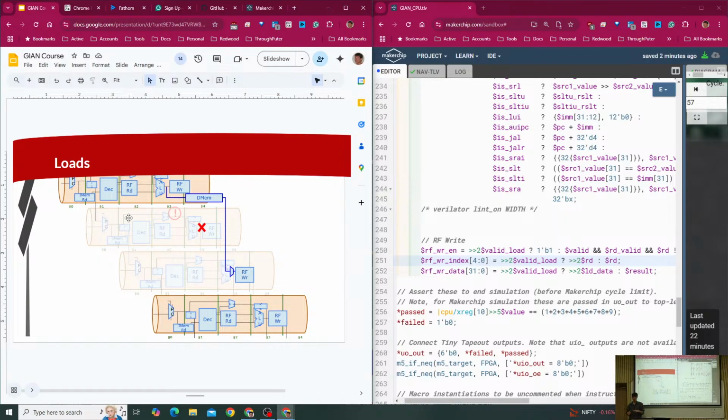That tends to be expensive. You have to inject into a lot of signals. You might have to change opcode values or the entire instruction depending where you figured that out. It's much less impact physically to the logic if you are careful about the control logic and use things like valid signals. So yeah, we factor valid into isLoad so that we only have this impact for valid instructions, valid loads.